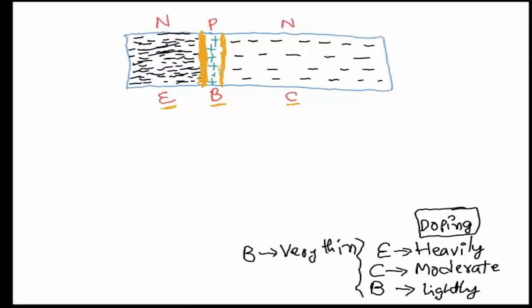And one on the collector. Yeah, it should be 0.7, either from base to emitter or base to collector, because both sides are a PN junction. Right? So a working transistor, or a good transistor, indicates this.